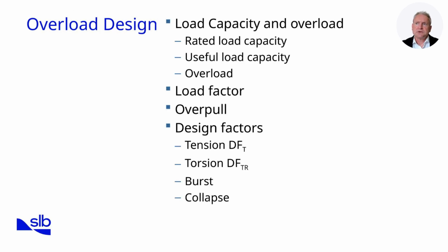Overload design ensures the drill string operates below its maximum rated capacity with appropriate design factors applied. The rated load capacity is the manufacturer's published limit, while useful load capacity is that limit reduced by the design factor. Key terms include overload, load factor, and overpull margin.